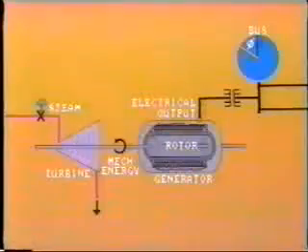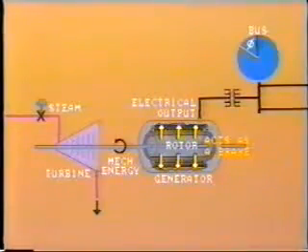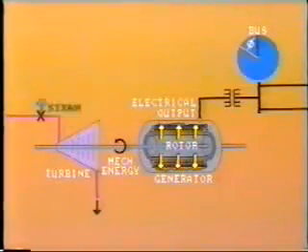When electrical load is applied to the generator, more current is drawn, consequently increasing the magnitude of current flowing through the stator windings. This current creates a flux which tends to act as a brake on the turning action of the rotor. In order to maintain the machine's speed and restore frequency, more steam must be supplied to the turbine in order to increase the mechanical output.